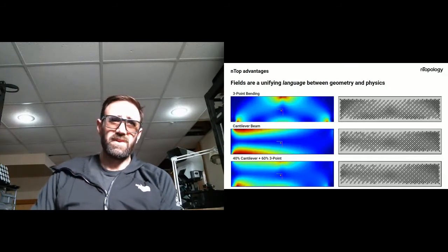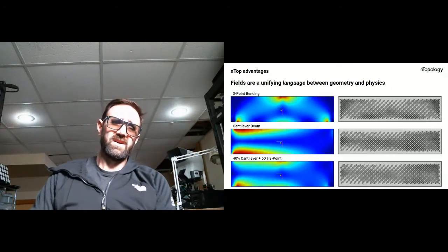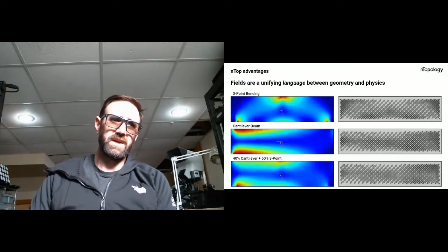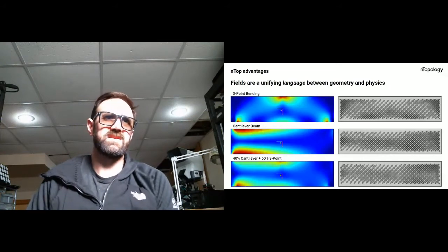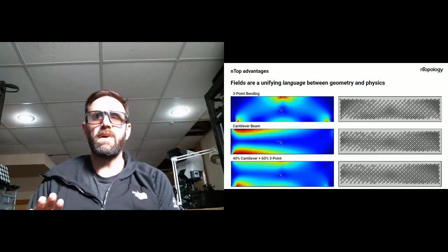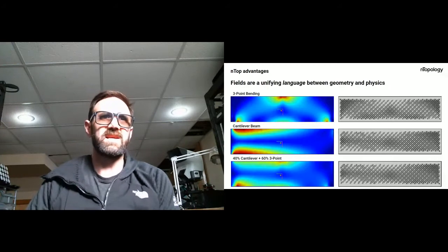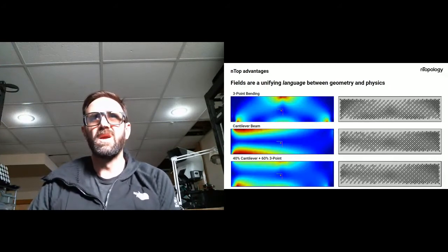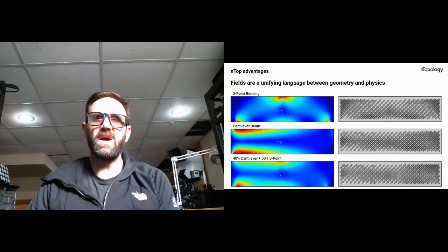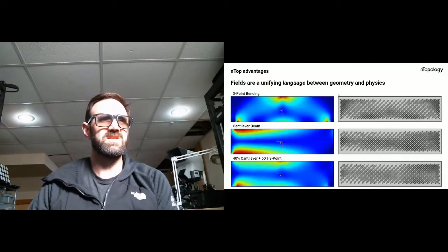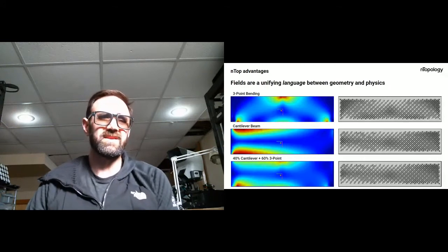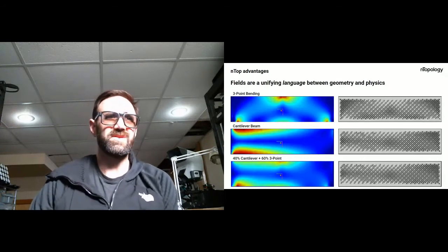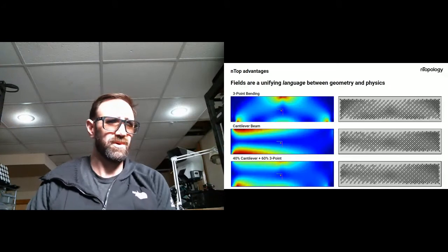So the idea or concept here is that we have a bar in different loading conditions, or excuse me, a beam. And in this scenario, we're using a stress analysis to look and modify our geometry, in this case, an infill for lightweighting, but we're going to selectively vary the thickness of this lattice so that at areas of high stress, we actually have more material. This goes back to the concept of lightweighting. It's just putting material where you need it and removing it where you don't.